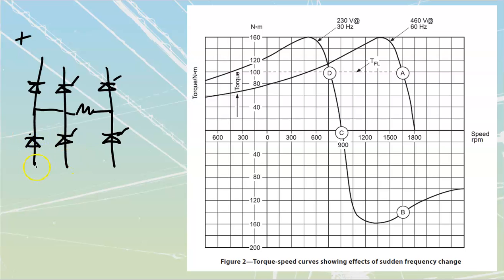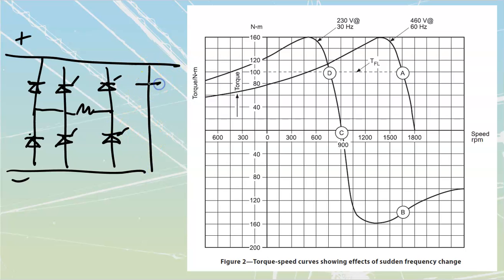So we see that they're lined up over here because that's going to be my negative bus. This is my positive bus over here. And same with these ones over here and over here. All that this allows us to do is utilize each one of these to kick out those values of voltage, to kick those things back out onto my DC bus every time that we would collapse, because normally we're going to have current flow.